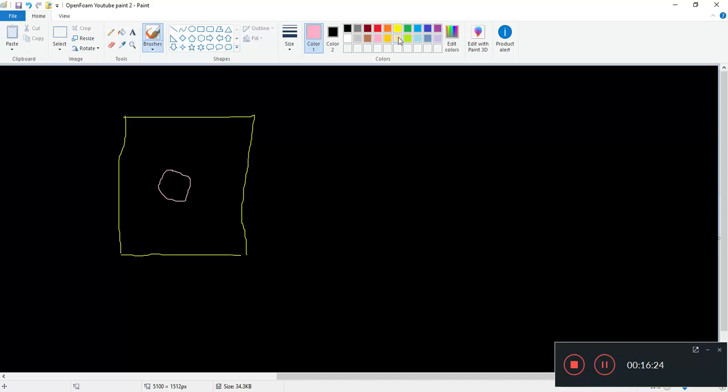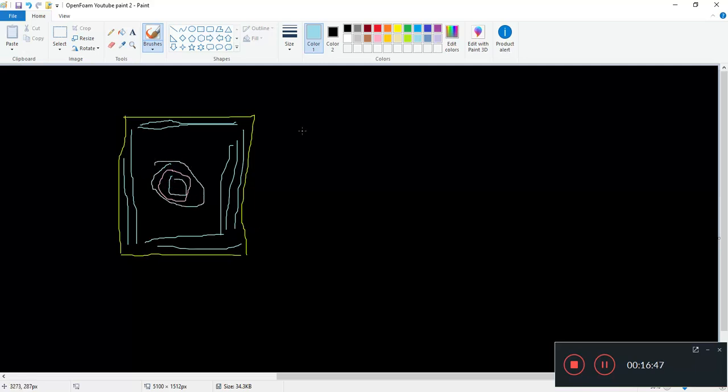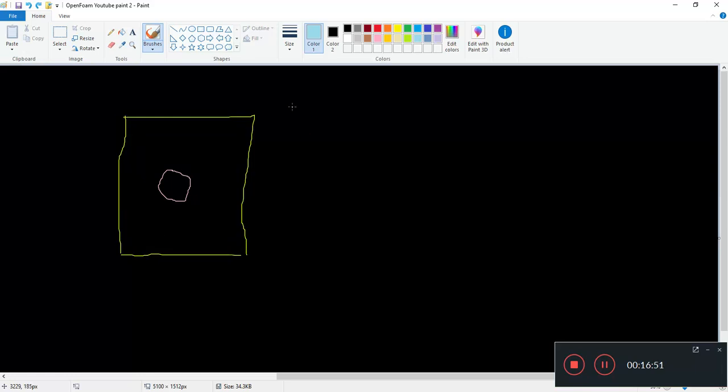If you don't specify how you want to add layers, OpenFOAM or snappyHexMesh will say, okay, I'm going to add layers to every single patch, even though that's not what we really want. The only patch we want to add these layers on is around the sphere, because that's where it is critical to add the layers. So this is the one we want.